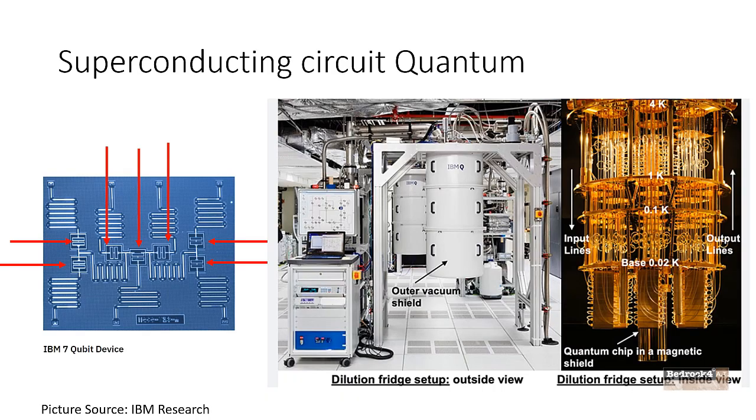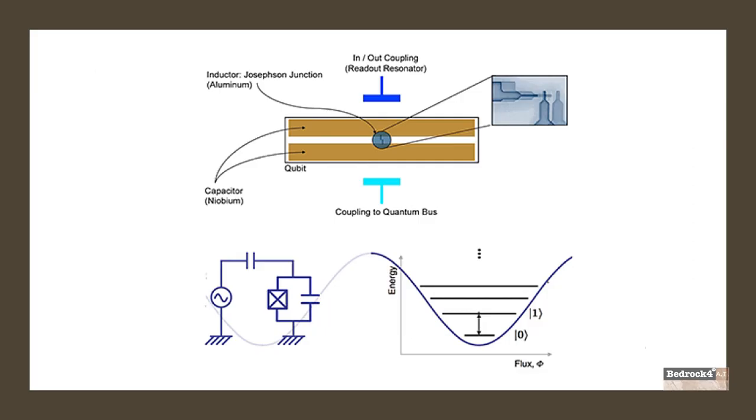In the case of a qubit created from a superconducting circuit, an inductor-capacitor circuit is used to create an artificial atom such that the energy level of the LC oscillator can be controlled using microwave pulses. We discussed the LC oscillator in the physics section already. The spacing between the energy levels needs to be non-linear to replicate an atom. Hence, a special device known as Josephson junction is used as a non-linear inductor. Josephson junction works on the principle of quantum tunneling.